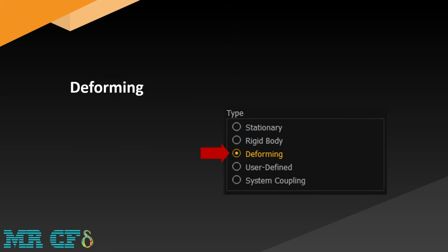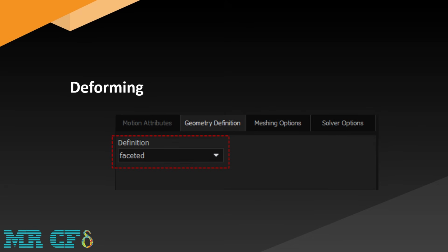The third type is dedicated to deforming boundary. It means that when we face a dynamic surface which is changing shape, we actually should use this model. For the settings of the changing zone, we must first determine from the Geometry Definition tab the zone of the computational domain of the model that we want to change shape.